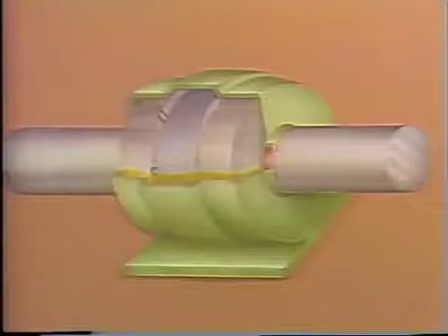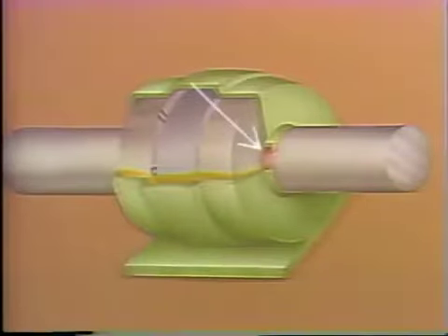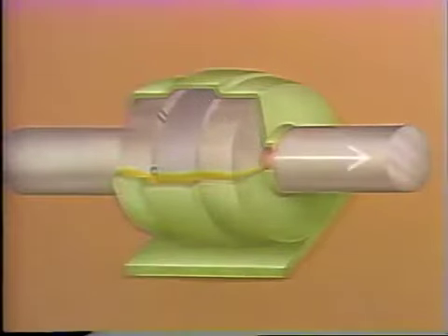They're held in place by a housing. The housing can't move because it's usually bolted in place. The housing also contains grease or oil that lubricates the bearing surfaces. Seals located where the shaft penetrates the housing keep lubricant from leaking out of the housing. Whenever the shaft tries to move axially, the collar pushes against the bearing surfaces and movement is stopped. Actual contact of the collar with the bearing surface is prevented by a thin layer of lubricant.